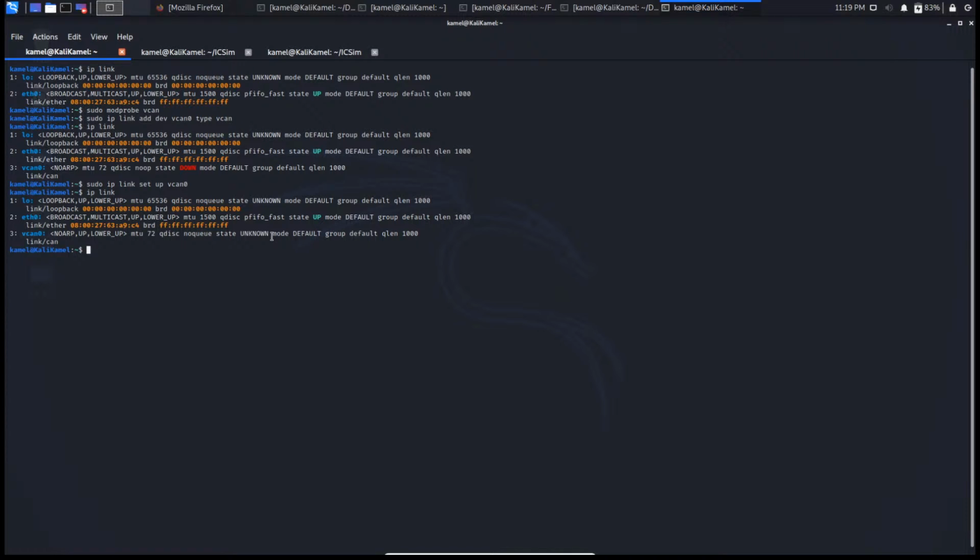modules instead. One thing I do want to mention is that this command here that we used to set up the CAN bus is the same one you would use for a physical CAN bus. You can use these software tools with a virtual CAN bus or with real CAN hardware that has SocketCAN support. A lot of devices come with built-in SocketCAN support, as in you literally plug it in and you're good to go. Other devices, you might have to do some tweaking, some adjustments to the software to get it to work, but there's a whole plethora of freely available software that works with these different devices. Although we're not using hardware today, please keep in mind that everything I'm going to show you from here on out is possible with hardware as well as with this virtual CAN bus.